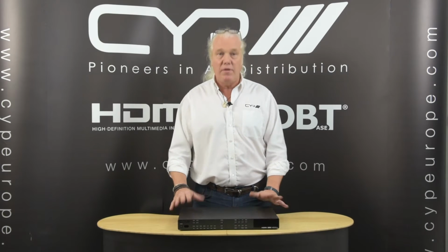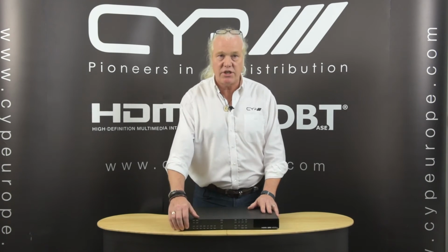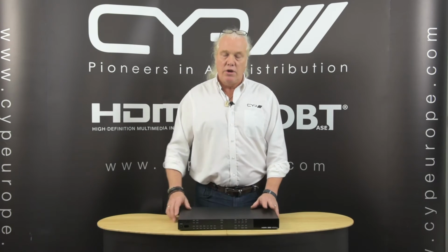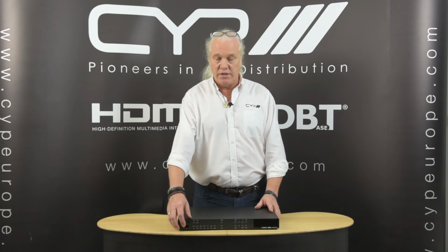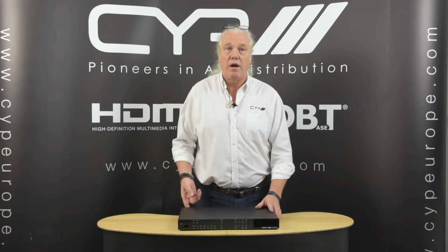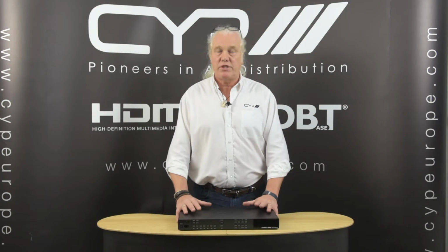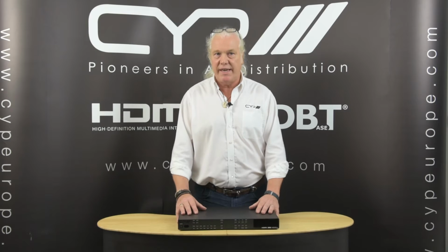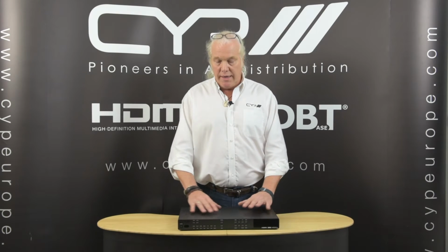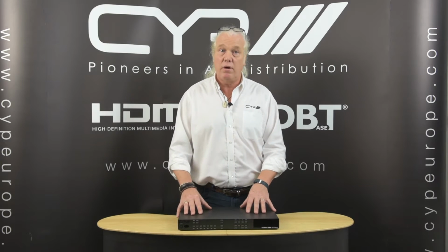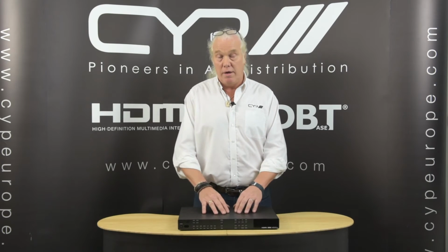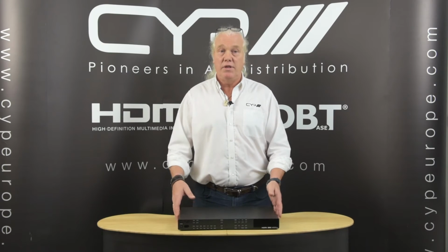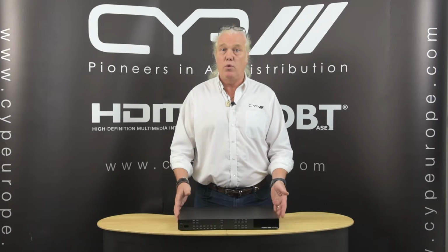Now the unit can be controlled by the usual means. There are hard keys at the front for selection and also to access the menu. You can control it over IR from an IR receiver at the front, and there is an IR input at the back for an IR receiver. You can control it over RS232 and Telnet. Now it also has a web GUI for control, but it also allows you to use quite a sophisticated EDID management tool. The EDID management tool allows you to copy EDID files from the screens connected to be used later on. Alternatively, there is an array of pre-stored EDID files that you can select. This allows for advanced video and audio management.